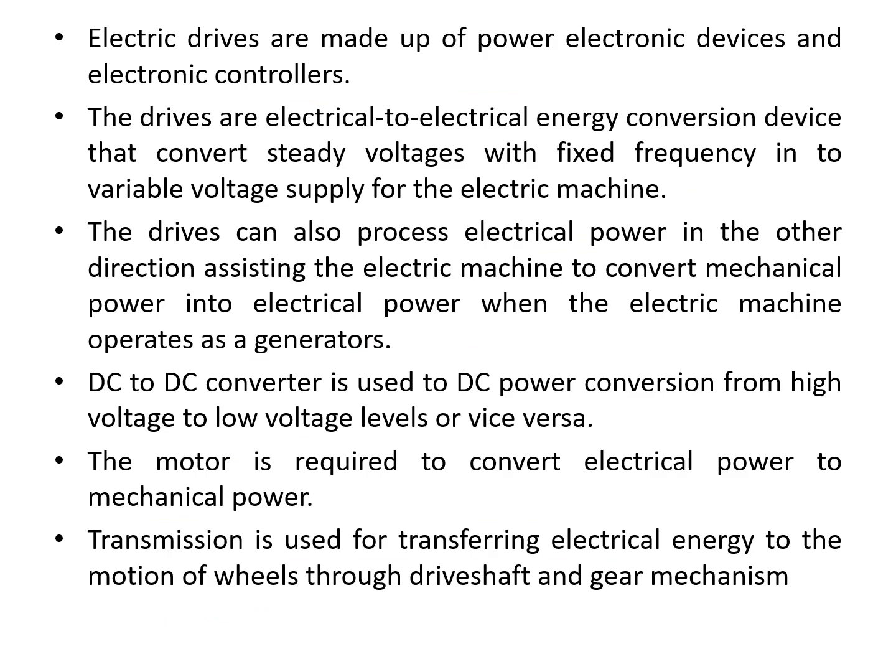Electric drives are made up of power electronic devices and electronic controllers. What are these electric drives? These are made up of mainly power electronic components, and then some electronic controllers, maybe sensors, thyristors, diodes, all these will be there inside the electric drives. The drives are electrical to electrical energy conversion devices that convert steady voltage with fixed frequency into variable voltage supply for the electrical machine.